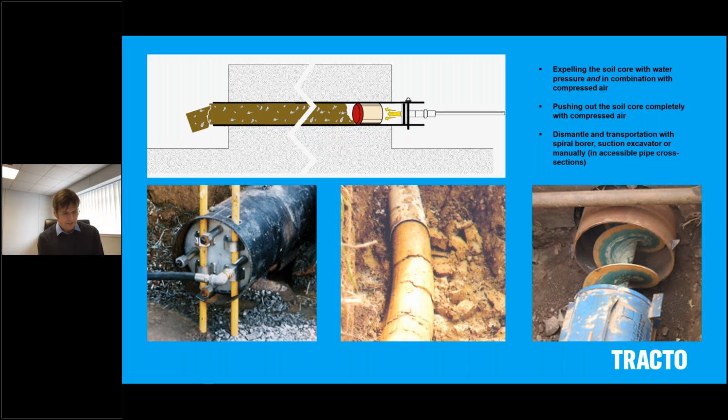A question that is sometimes asked is, how about big boulders? How do you get big boulders out? And what if a boulder gets stuck in the pipe? Well, whilst that is theoretically possible, it is very, very, very rare that a boulder gets stuck. Remember, the cutting shoe serves not only as a lead-in for the spoil, but it also helps to break up the boulder. So generally it doesn't get stuck.